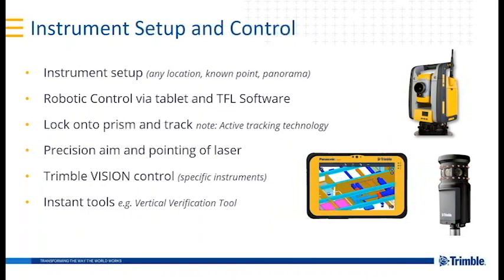So the instrument setup and control, so it works the same way as you would using a surveying instrument. So you do a resection, you set up using existing control points that are out on site, and then you control it all through the tablet. So we use the same technology with a prism. And then we've got a laser pointer for setting out.